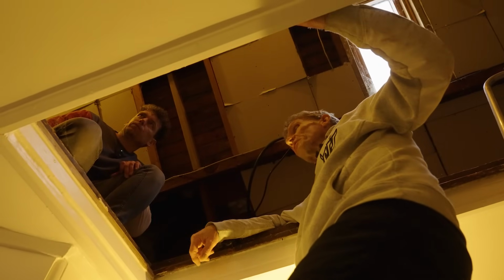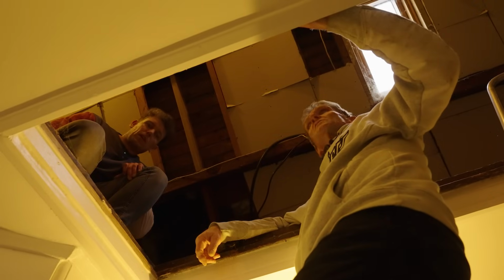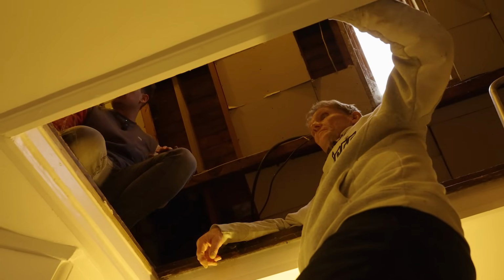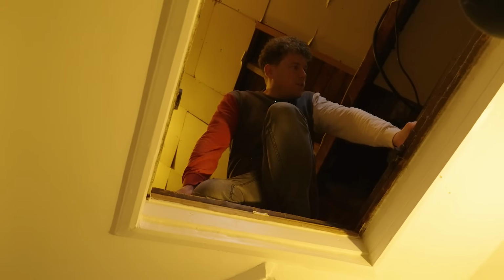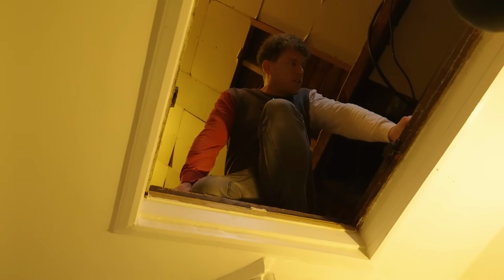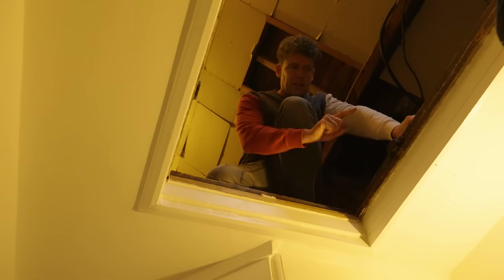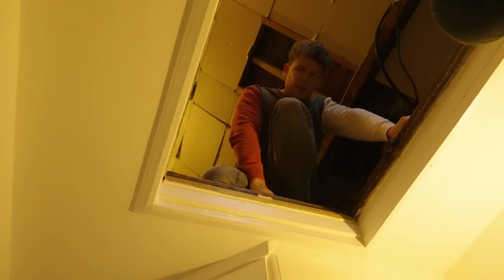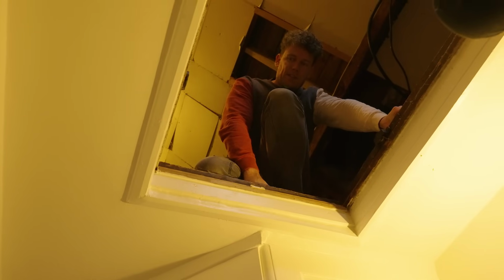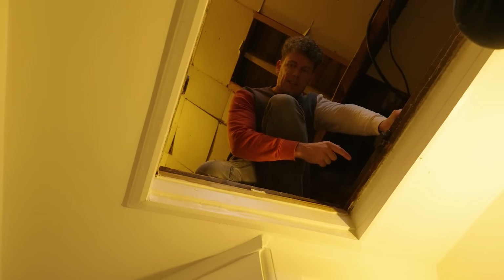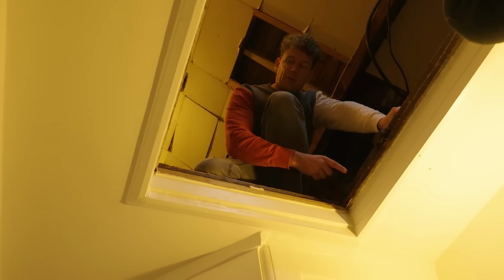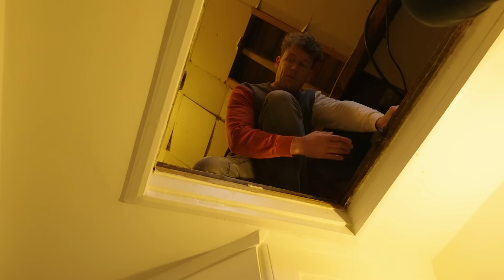It's difficult though because it's all boarded out, so all those boards have got to be lifted. Not everybody's favourite job. That's another reason why your running costs are high. I'll tell you what we're going to be able to do, John, is create 2 versions of your house in our digital app, and we're going to be able to insert your loft, that's going to be heat loss, and this is going to be your savings. And remember, you're going to lose less heat, so that's less energy, and your flow temperature from your heat pump can be lower, so it'll be more efficient as well.